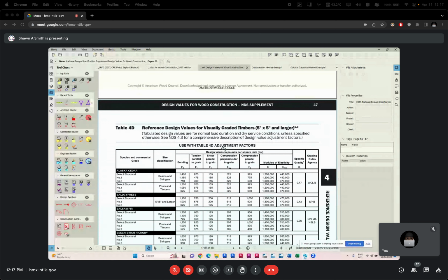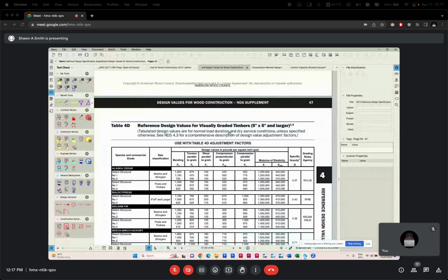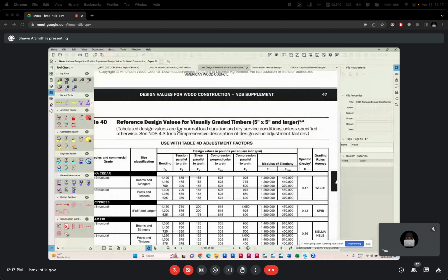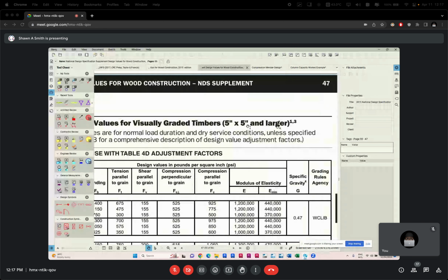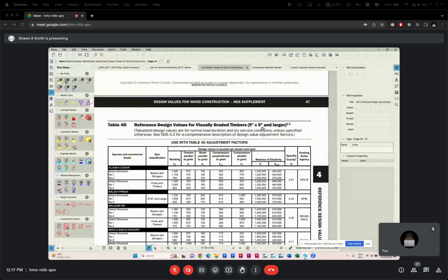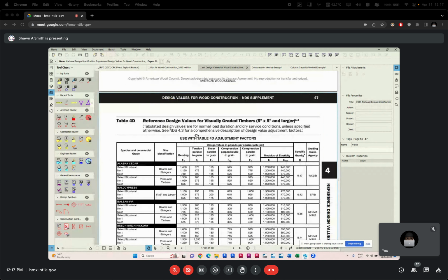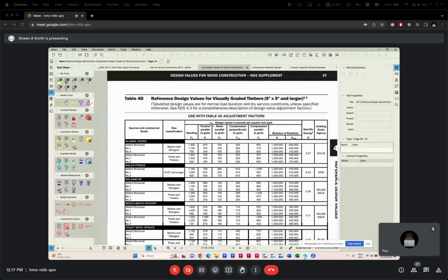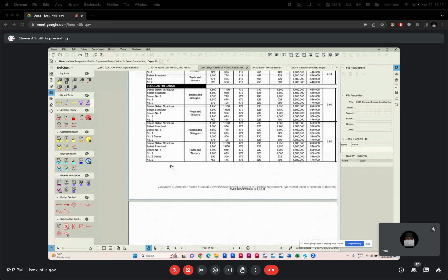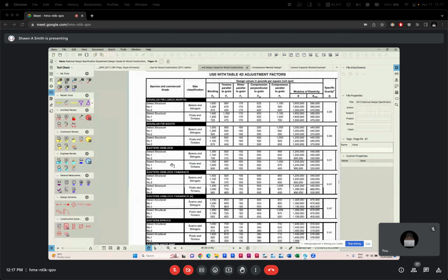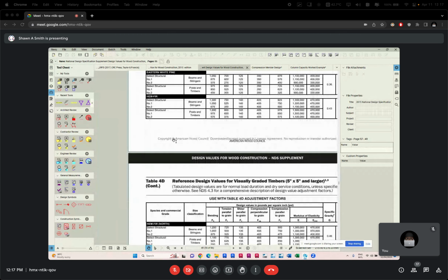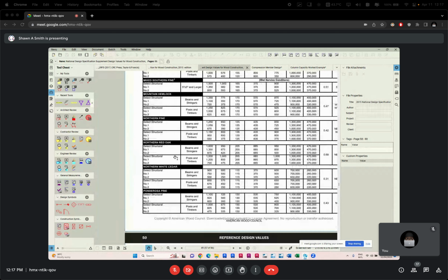Oh, class. So this is discovery. There's a separate table for timber elements 5 by 5 inches and larger. So that 6x6 actually falls within this table. And there's no stipulation here to say whether it's pine or not, because in this table there is Southern Pine, I imagine.